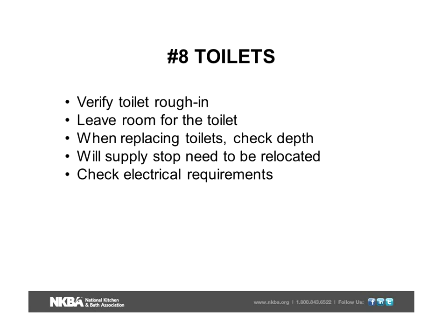As far as the toilet is concerned, we had several things here. Verify the toilet rough-in. Leave room for the toilet. When replacing toilets, check the depth of the toilet. You're going from a standard toilet to an elongated bowl. That can create a problem.